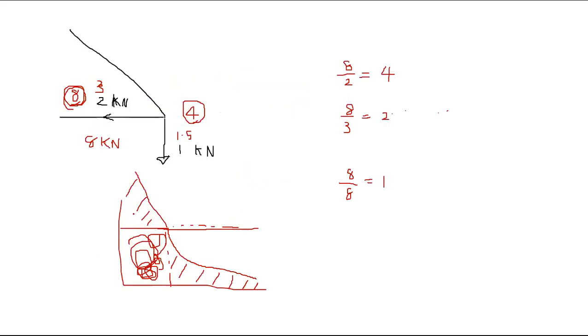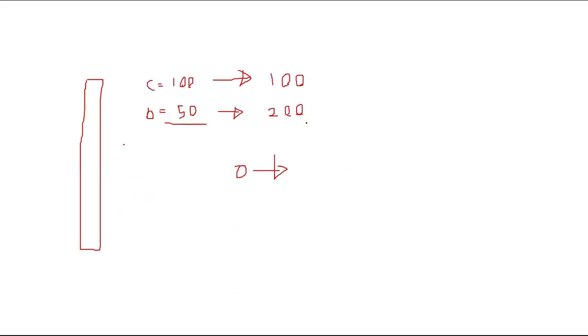Now you are in this region, where the compressive strength of the material is less than the stress that can be withstood when buckling occurs. So it will fail by crushing before reaching buckling, because the lower value is now this.